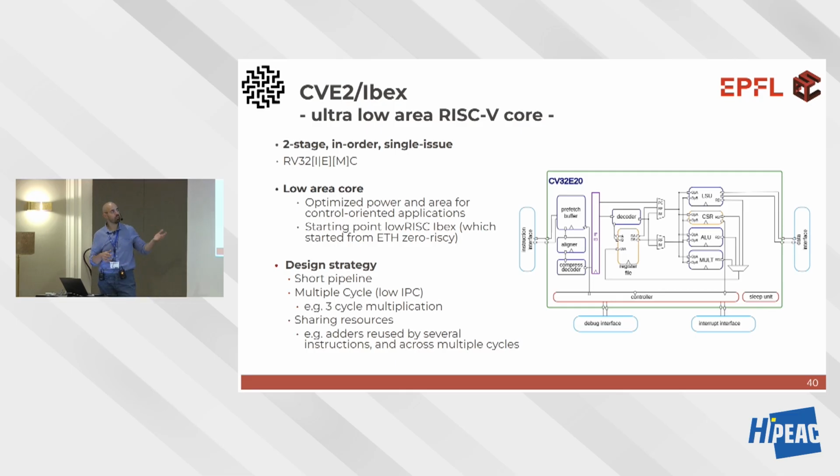Okay, so looking at the CPU, we already figured out that there's a prefetch buffer for the reason we said before. There's an aligner that records the states and tells us whether it's a compressed instruction or not and where it starts from. And that's a design decision. You don't have to do it like that. Actually, I played with this parameter as well.